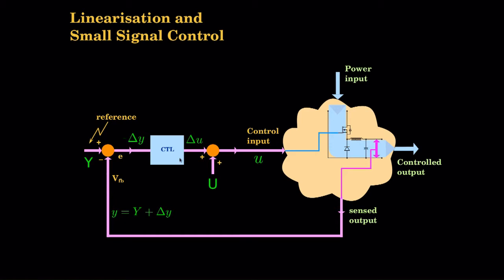So, you see the interesting difference here is that the controller is going to only operate on small signals. So, the stress on the controller is much lower, and the time taken to reach its steady state will be smaller. So, the dynamics also will improve, and more importantly, you are trying to give a linearized approximation.